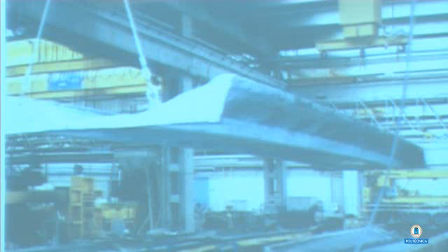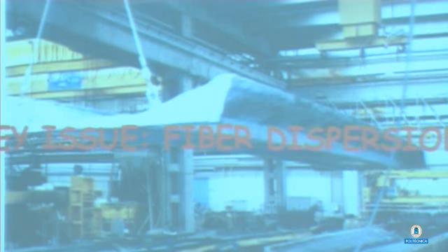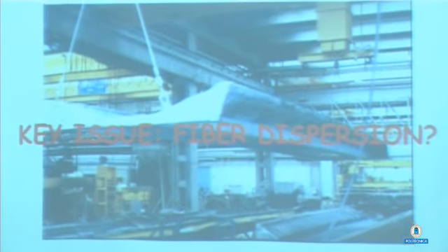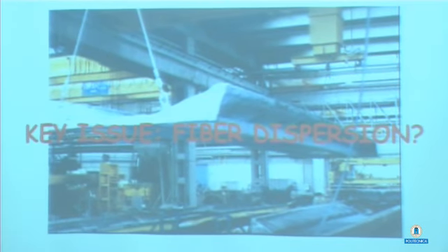Obviously, one of the key issues that you need to control in order to ensure the safe and reliable behavior of this kind of element, when you remove steel reinforcement and put fibers, is that fibers are very well, let us say, randomly or homogeneously dispersed inside of this element. Because if you have a spotty dispersion, you can have regions without fibers, because vibration and compaction can hinder this homogeneous dispersion. Those spots may act as flaws and may trigger the failure also for lower values of the ultimate load than you were able to calculate according to the design.